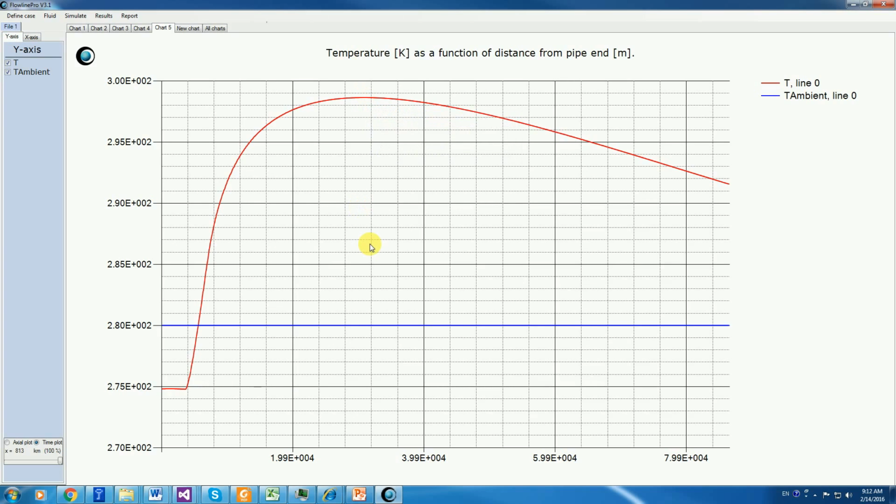Well, the part of the gas which is captured in the gas pipeline when we close the outlet valve is being compressed more and more. And compression, when we compress a gas, even a perfect gas, it becomes hotter and hotter. So that compression leads to the temperature going up. And that continues as the pressure goes up more and more until we reach a point where the temperature loss to the environment becomes higher than the further increase due to the pressure still going up.